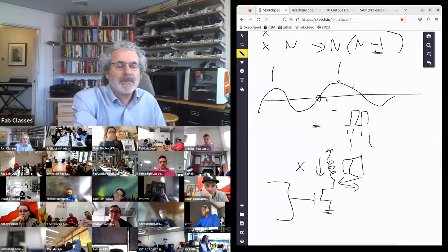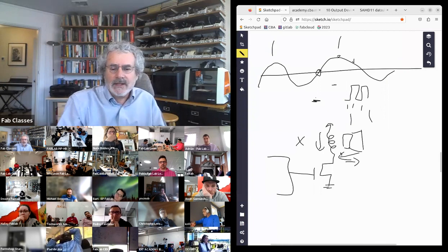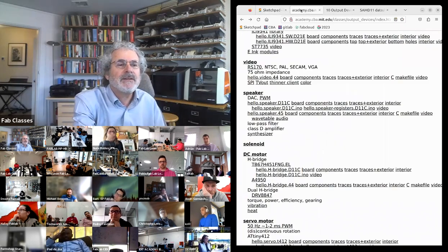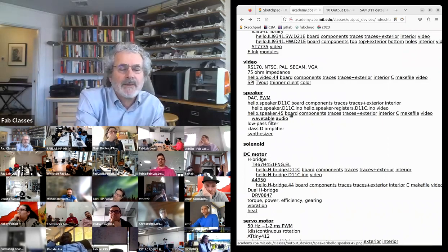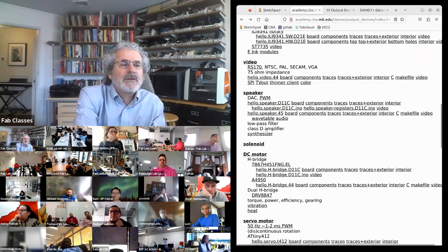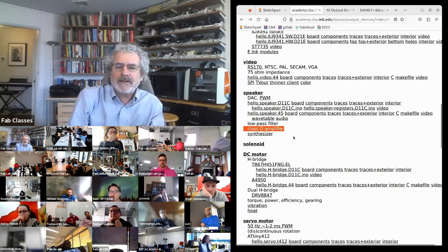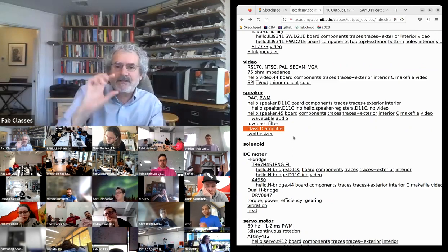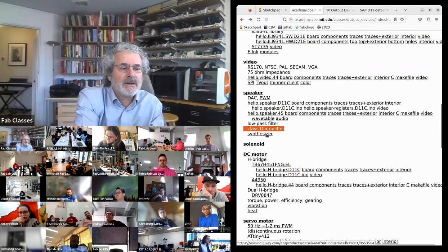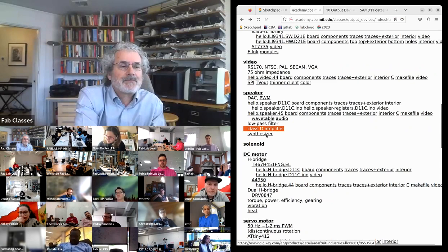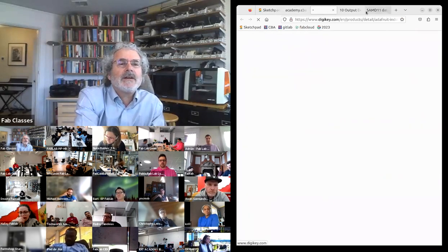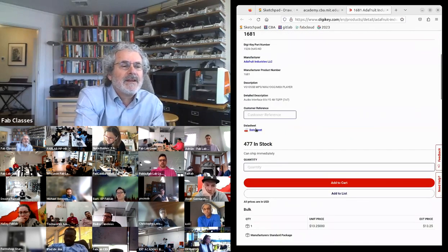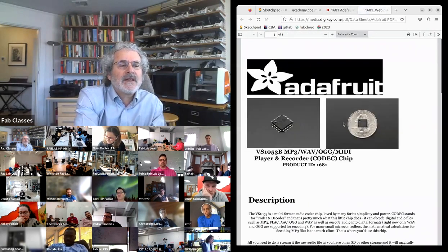and it's good for a beep. Better than that would be, you'd like to drive the speaker with current going in both directions. And to do that, you need to use a part we're going to talk about called an H-bridge. And what's called a Class D amplifier is essentially driving a speaker with an H-bridge, which again, I'll talk about in just a minute.